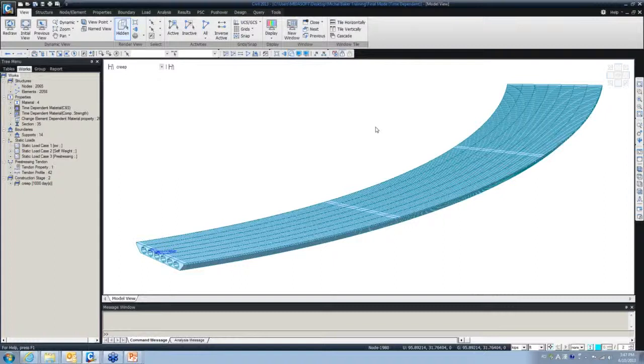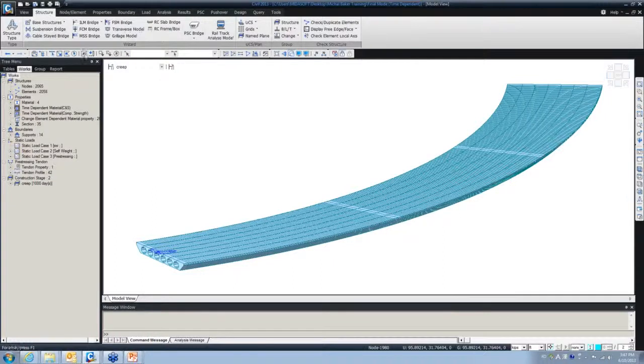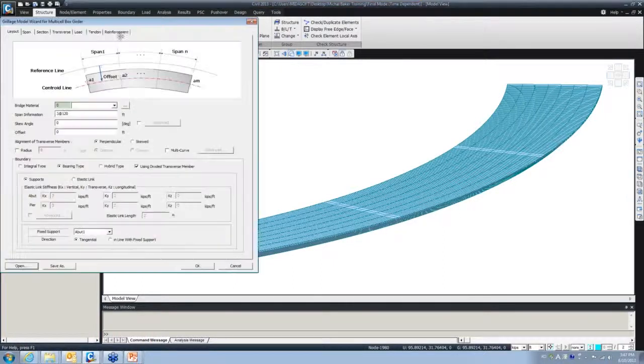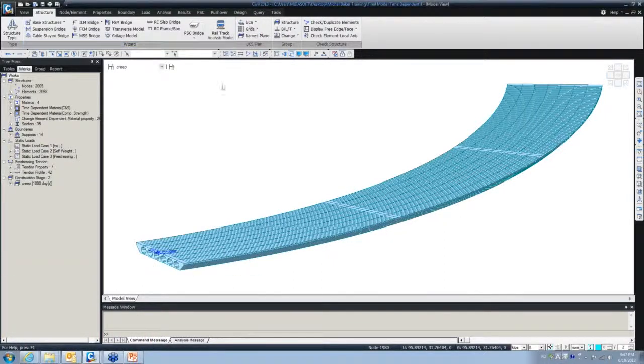So this way you saw how we can use grillage modeling to create such a model. And that's exactly the same as other types of modeling. If you want to change anything, you can simply change it. You want to add anything, rotate them, change the material, change the coordinates of the nodes and elements, you can easily do it. Anytime you use these wizards, you are completely free to change anything. All right, this is the first method.